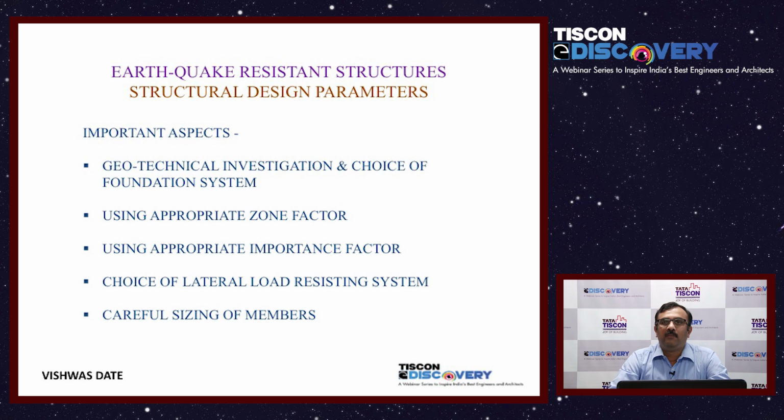So again, when I mean sizing, architects always complain about higher column sizes. That's why we try to squeeze column sizes, maximize concrete, maximize reinforcement. Does it always work for us? May not. So that's why we have to again look at how best we can suit both the requirements. Maybe you need to have another column just to avoid the overall increase in size. We might have to do one or two iterations to arrive at the final structural scheming.